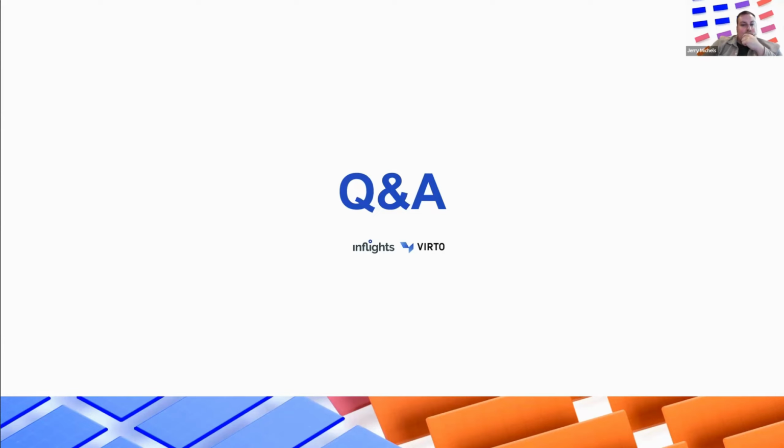Okay, and let's see. Next, how can we calculate ballast? So basically how the ballast works is that with those companies like Avasco, Van der Valk, CPX, and a few more are on the way, by the way, we have created together with them an API that can calculate the ballast according to all of their settings. And because we created that API, it's also integrated within VirtoCAD. The same tools you can find on the website of those mounting system suppliers, and the calculations are perfectly the same.